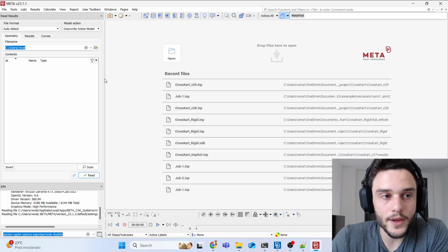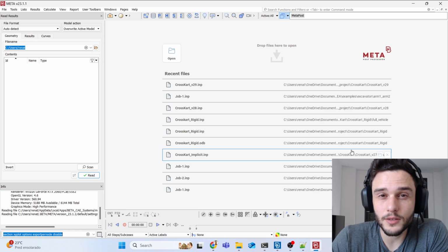Let me point out again that if you want to read Abaqus results here in Meta, you should install the Abaqus library. Okay, if you don't do this, you're going to have an issue. So this is another thing that you should find and install. Okay, let me tell you that it's not hard to find it.